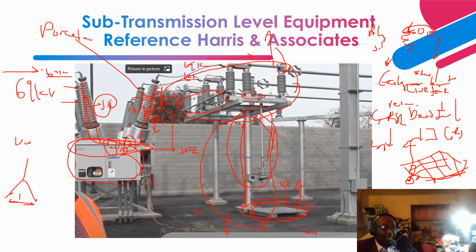One leg is here, another leg is here. If they are separated by 1 meter, the voltage difference is what they call step potential. It has to meet a certain criteria based on IEEE standard 80. And there's something they call touch potential.